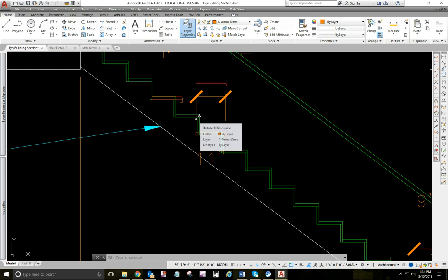Okay, now treads and risers. Risers in residential are typically 3/4 of an inch thick, and the height of it will be cut to however wide it needs to be. But they're typically cut from a 1 by 8. It could be a 1 by 10. It all depends on the stair design.